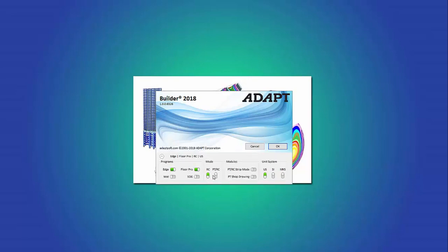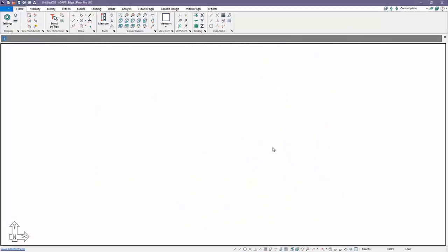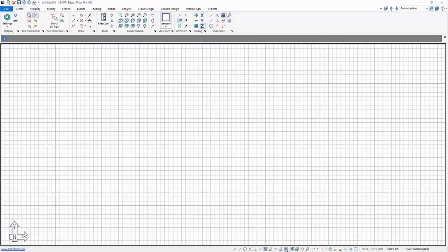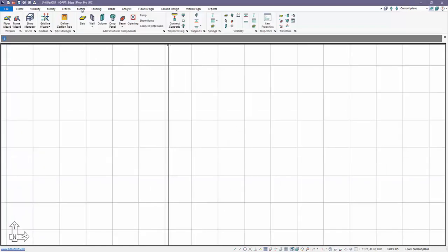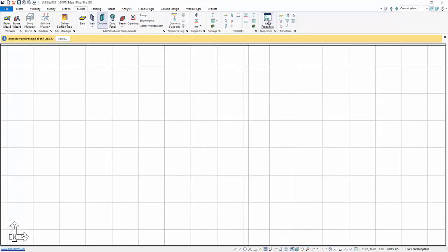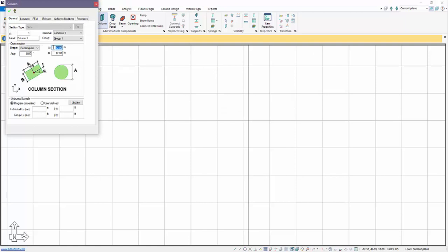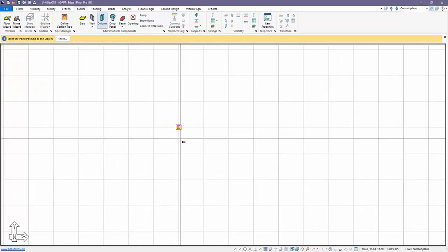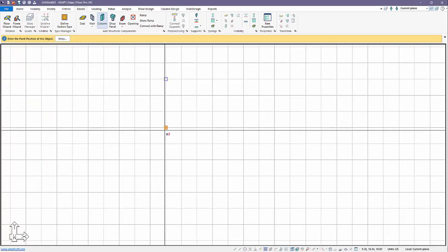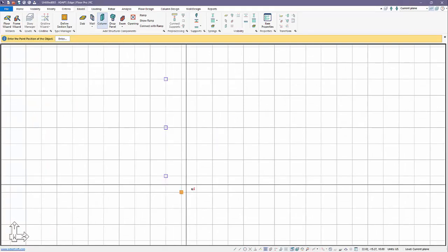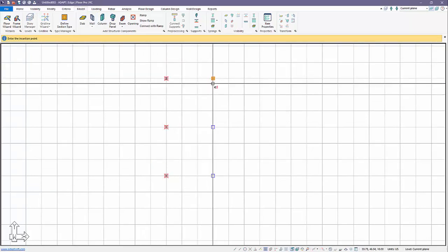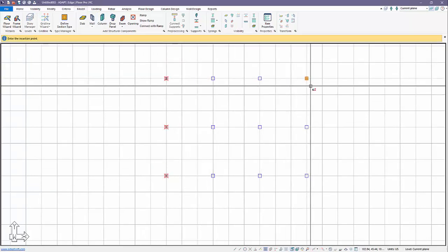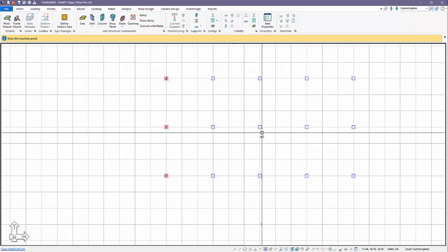We're going to do this relative to an RC model. We're working in Floor Pro for this example. We're going to set up a grid here and we'll use 10 by 10 spacing. I'm going to model 24 by 24 inch columns, and we'll do two 30-foot spans. And we're just going to go ahead and copy those columns over. Also 30-foot bays in the X direction.